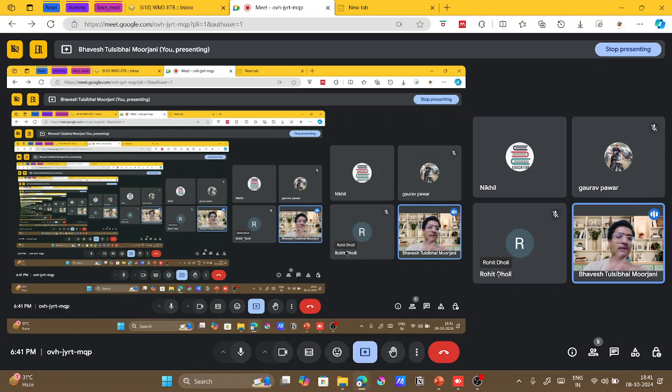Okay, so here once the equilibrium is achieved, the composition at the feed inlet and the composition at the product outlet will remain the same. So that steady state is achieved. Dynamic will come when you have feed composition changing with time, then your product composition is changing, or pressure fluctuations are there in the system, then it will become dynamic. So currently all the simulations that we are doing, we are considering steady state. Okay, but in actuality there might be some changes. Let's say in your distillation column pressure fluctuation might happen, so that will become a dynamic part. So accordingly your feed composition will change, sort of a thing, right?